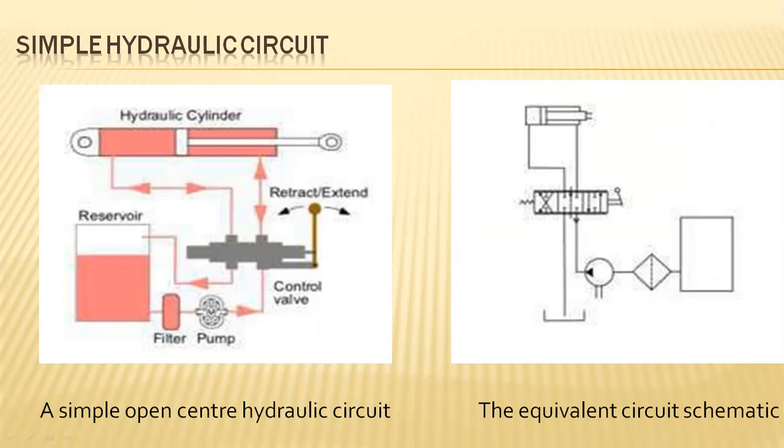So there are three different steps, commonly connected in the middle. This is the directional control valve which, for extension, connects from this port to this port. With ports numbered 1, 2, 3, 4, port 4 to 2 will be connected, energizing the forward stroke, and the fluid leaving the actuator is connected from port 3 to port 1 and drains to the reservoir.